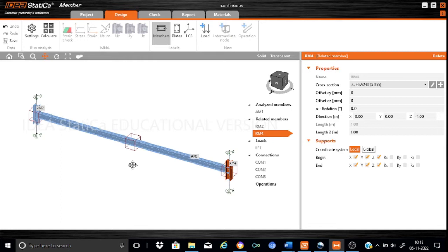In this case, as I have already explained in the first 2 pages, this is the analysis of a continuous beam with 2 spans, and I assume that this beam is only restrained at the support location. That means in the 2 span locations, it is not restrained at all. The spans are not laterally supported, and the support is provided only at the intermediate location.